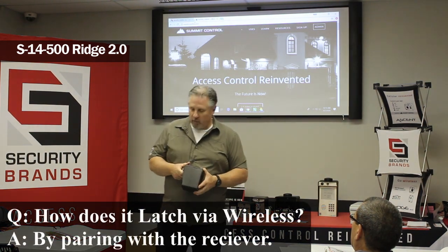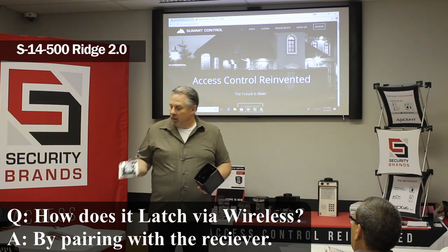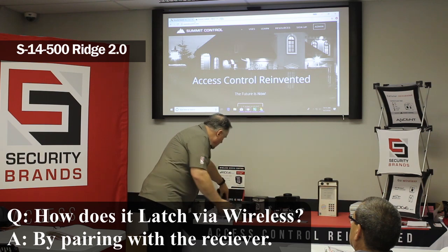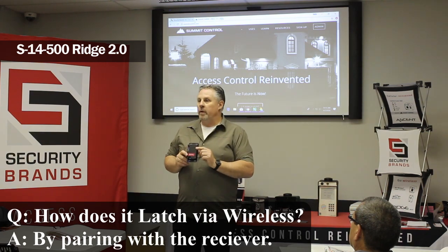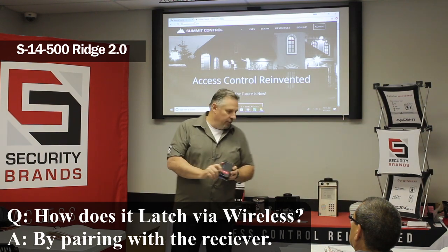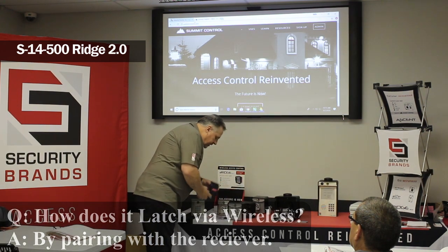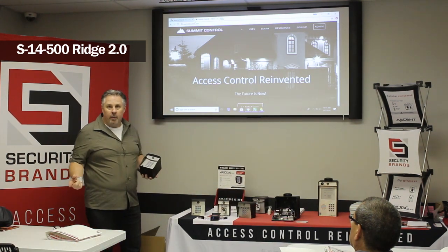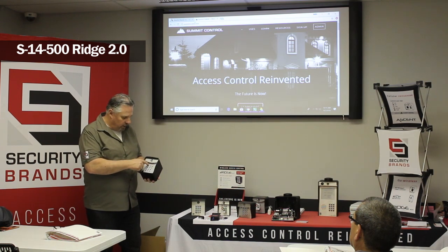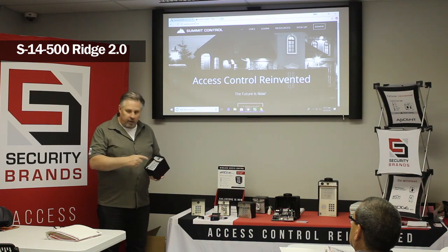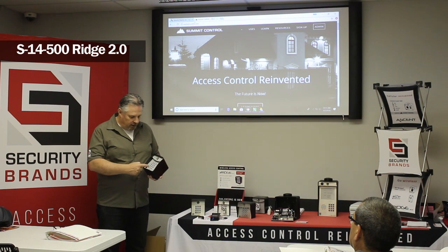You asked the question, how do I do a latch code? Again, 9-volt battery, 500 foot of range. The system comes with my receiver. This is a single relay receiver. So let's set this right here. I got a piezo on that, I just opened the gate, and I put in here 3214. So now 1251, 2 to delete codes, 1236, pound.